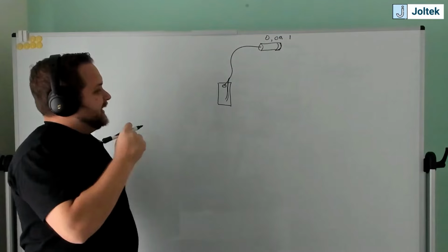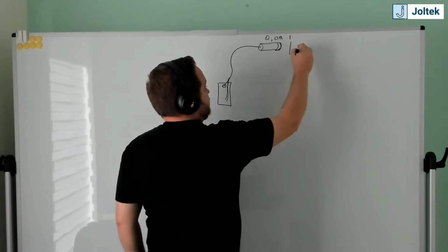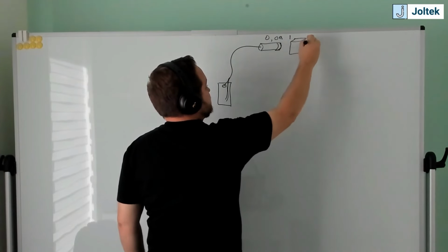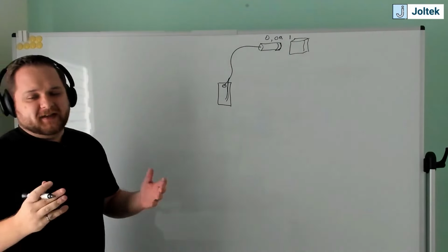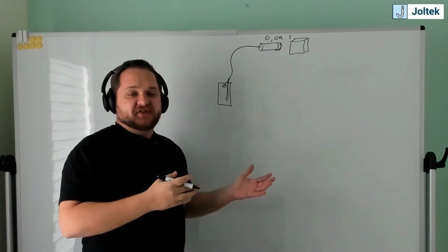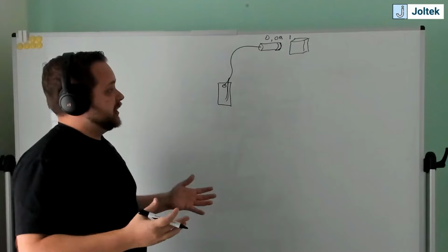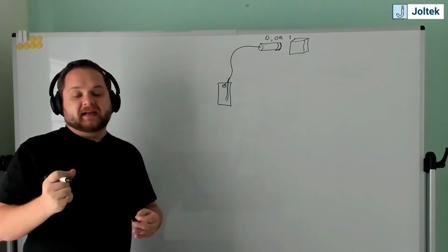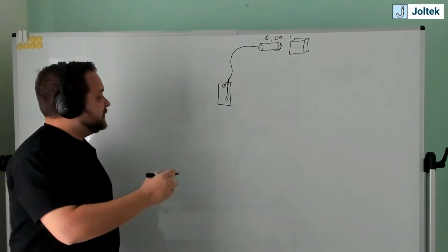Now, how is this signal generated? If something is in front of the sensor, right? So if I have a box in front of the sensor, then the sensor is going to send a 1 or a 0. Again, you can set it to send a 0 when the box is there. You can set it to a 1 when the box is there. That doesn't really matter. But when the box is there, it's going to send a high. When the box is not there, it's going to send a low. So what happens at that point, right?